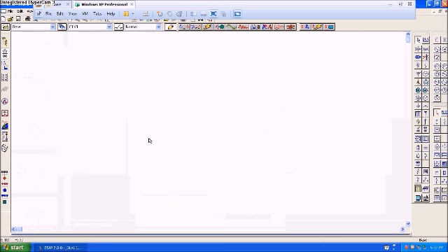Now as you can see, we have launched ETAP version 7.0. I'm going to design the circuit. I will just show the outline of the circuit, then we'll show you how to insert the values. So we have taken a bus from here. I'm taking a transformer from here. We have to take a feeder which will feed the bus, and then we'll take another bus. We'll take an overcurrent relay, a current transformer, and a circuit breaker.